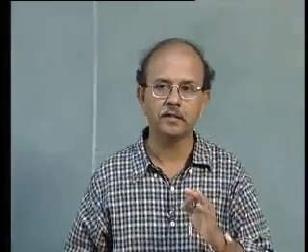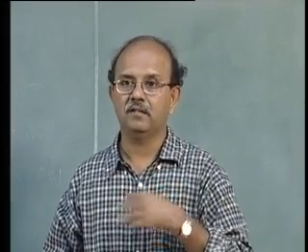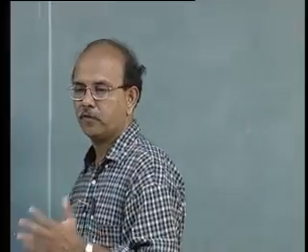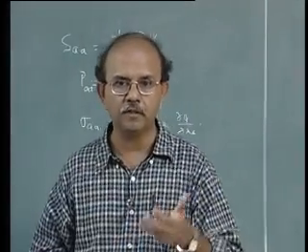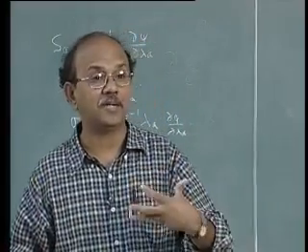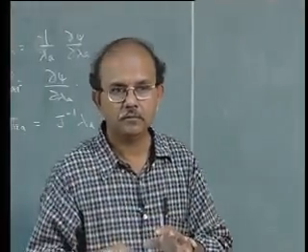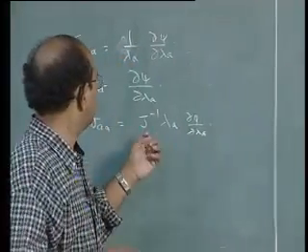If you remember, this was the result of my representation theorem. It stated that for scalar valued tensor functions, if isotropy is going to be satisfied, then it would be possible for us to write this in terms of the invariants. From there we wrote a very general equation. So that equation is valid for all isotropic materials. From here we are going to again branch off. Now before we branch off, we